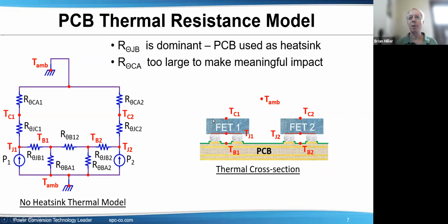With a GaN FET, there's basically a silicon wafer with a GaN layer put on it, and that's the way it's sold. There are some additional, very thin protection layers, but that's basically the way you have it. So yes, you're right. You could start with the same basic die, but to make it usable in the form you'd use in the design, that's the asterisk the MOSFETs have to deal with: what you end up buying and putting in the design.